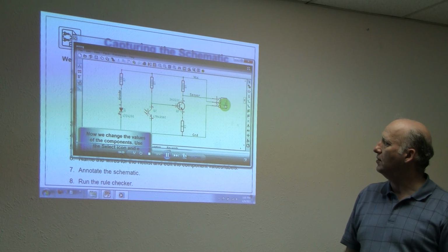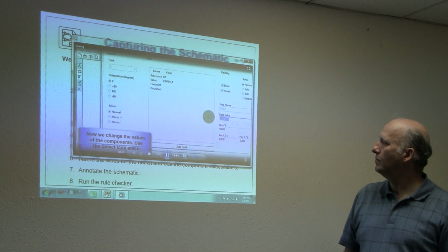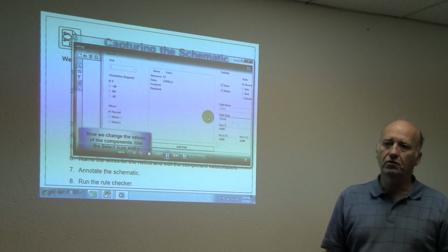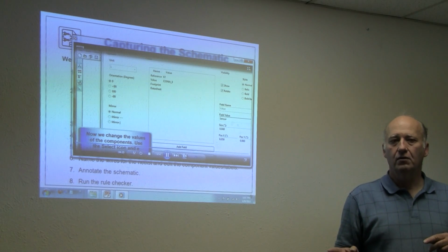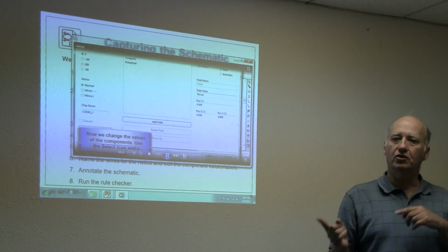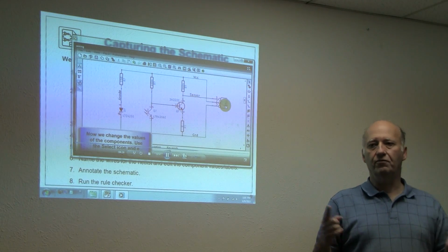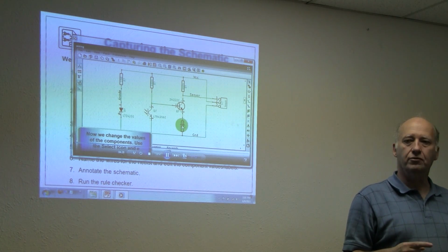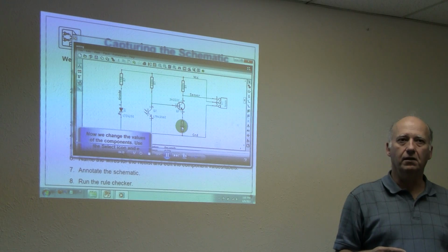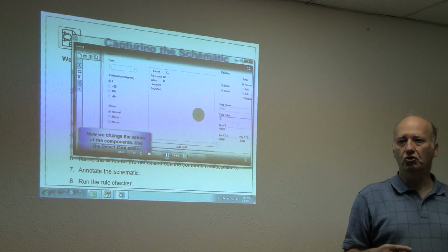Okay, so I'm going to name the connector sensor. And you want to do this, by the way, in the schematic before you move on. Because whatever you have here is what's going to show up on your silk screen when you go further. All right? And a good example in the little wanderer was I had the component named switch.